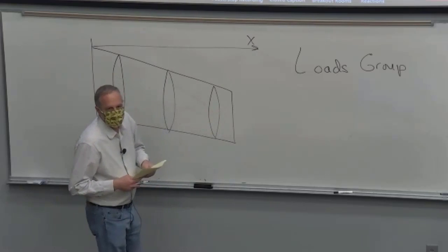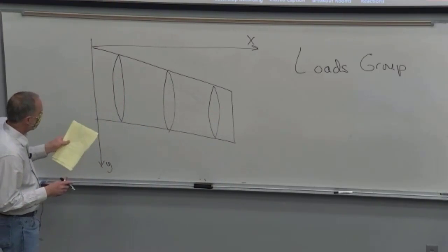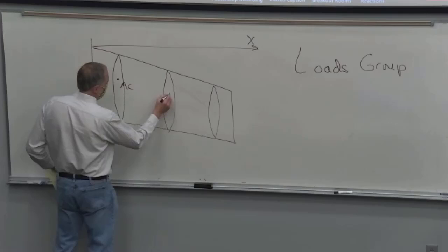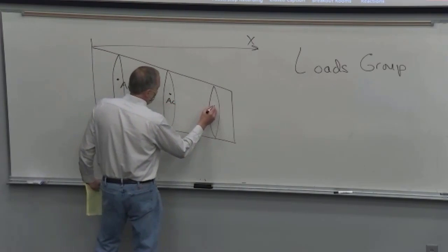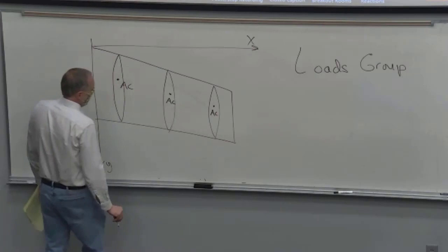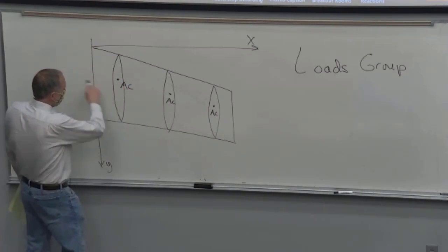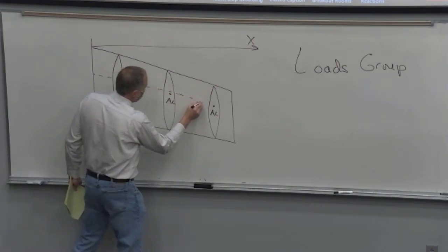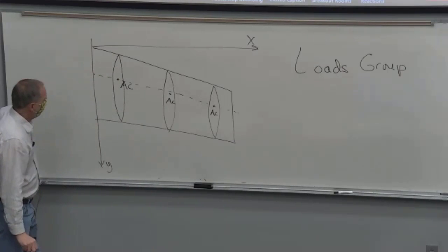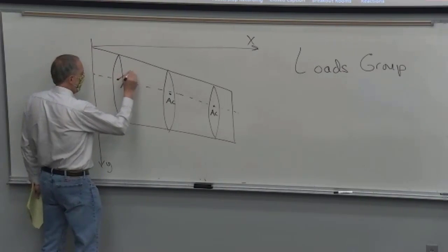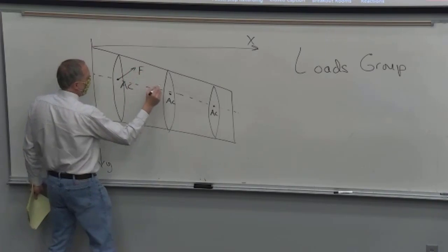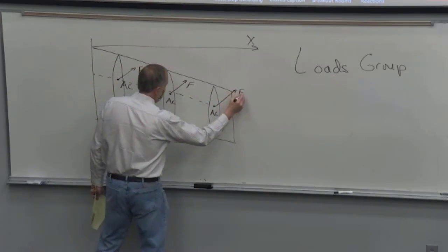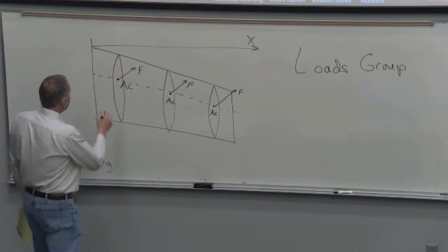So like I said, the structure of the wing, how it's put together, complicates this calculation, but at each airfoil you have its own aerodynamic center. And notice I've swept the wing, so that means that the aerodynamic center of the airfoil is not lined up straight across. There's a line of aerodynamic centers going through like that. And so each airfoil has a force acting at that aerodynamic center. And there's a pure couple.